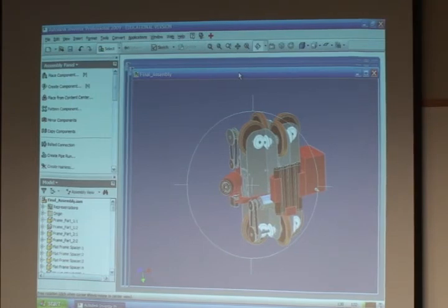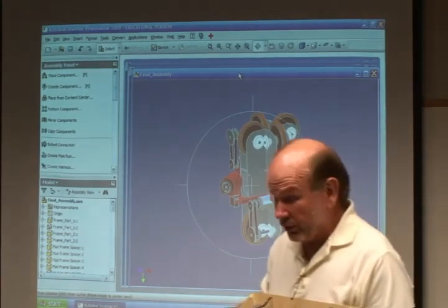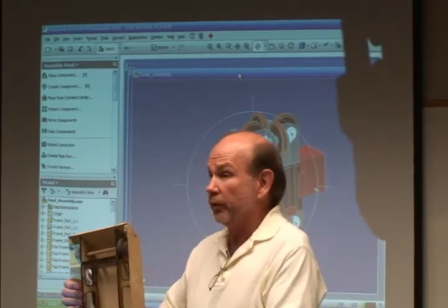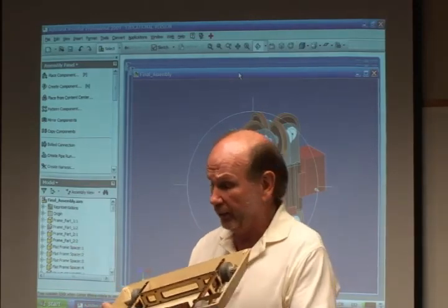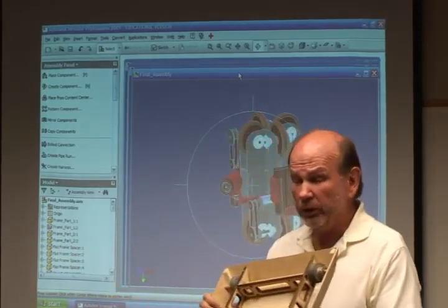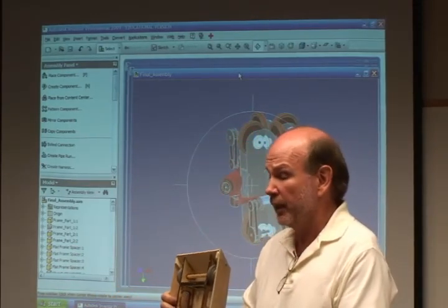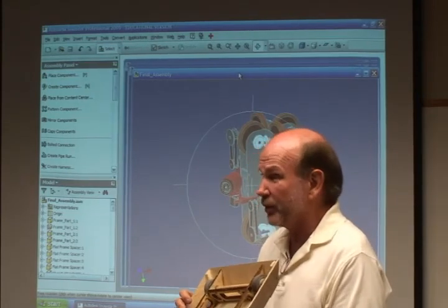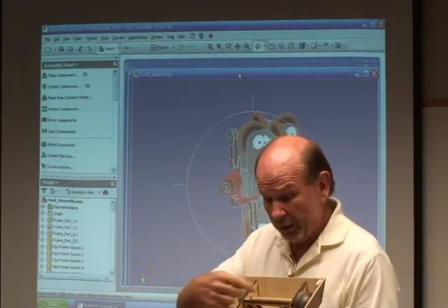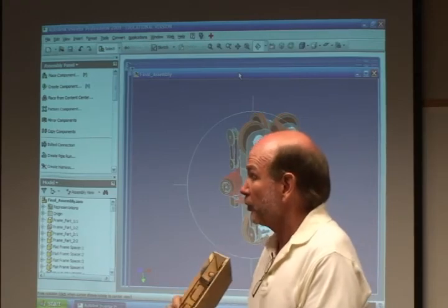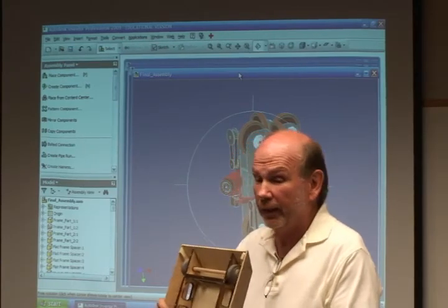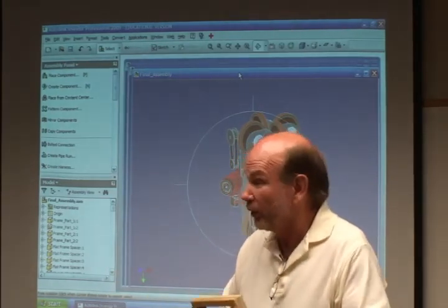What we have done, and it's really helped out in the past, is even after you design it and everything looks like it's going to work, we started cutting these out in the wood shop, and then we went to using a Legend engraver laser to burn these out. This is a great way, before you start cutting metal, to make it out of wood and make sure that all your components are going to fit and that things are going to work the way they're supposed to work.